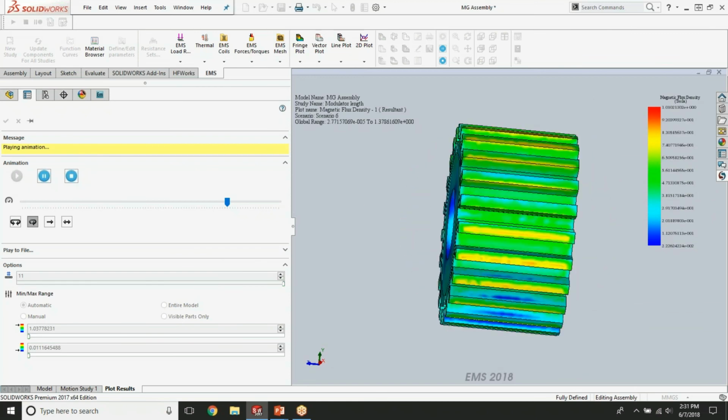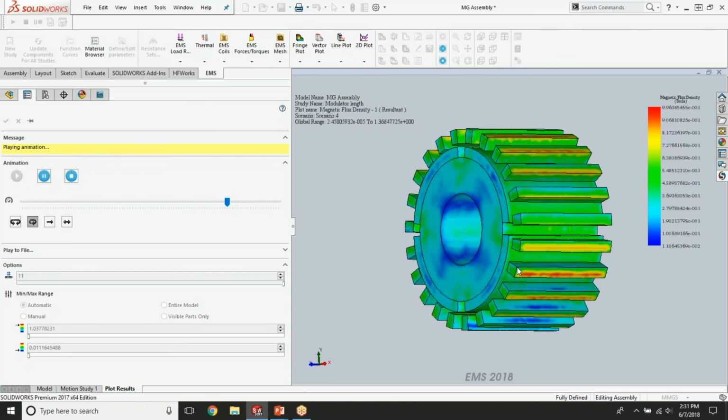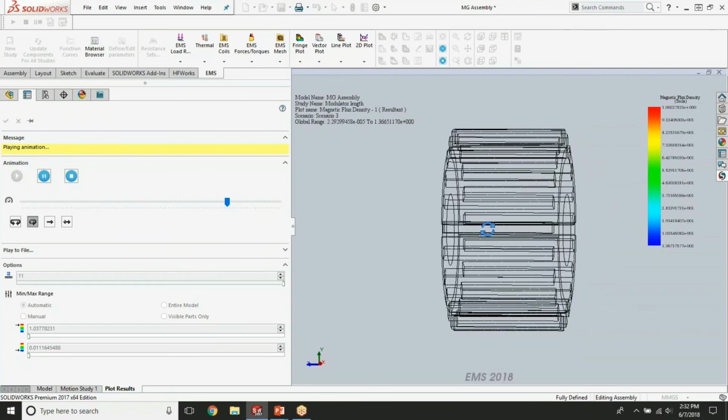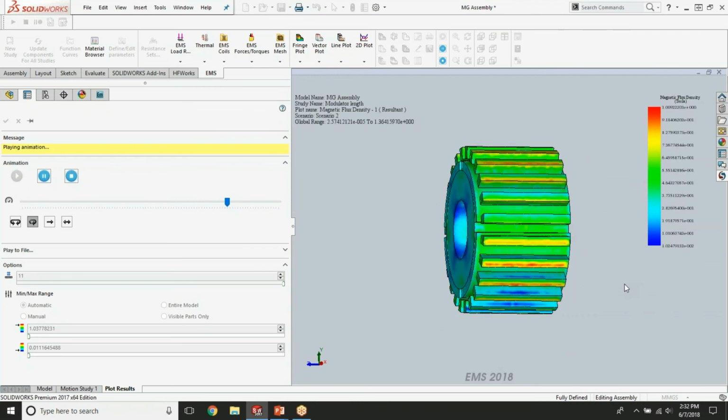Based upon the technical engineering literature, we can expect the peak torque to be for a length of modulator pieces which is slightly under the length of the rotors, because in that case a slightly shorter modulator is going to keep the flux on the inside of your device and prevent it from going too much into the axial dimension, from leaking into the end frontal and rear zone of the air domain in front and back of the gearbox.